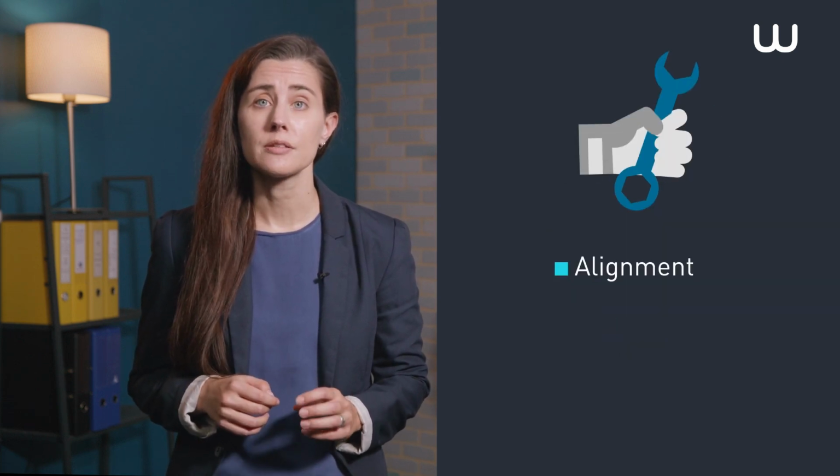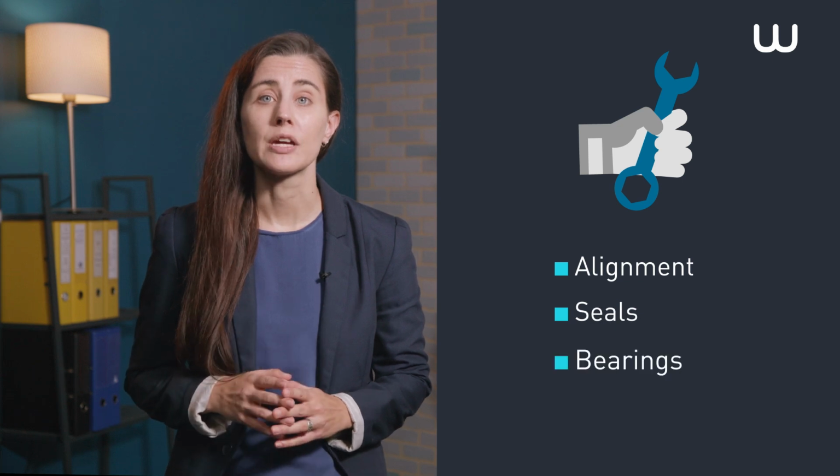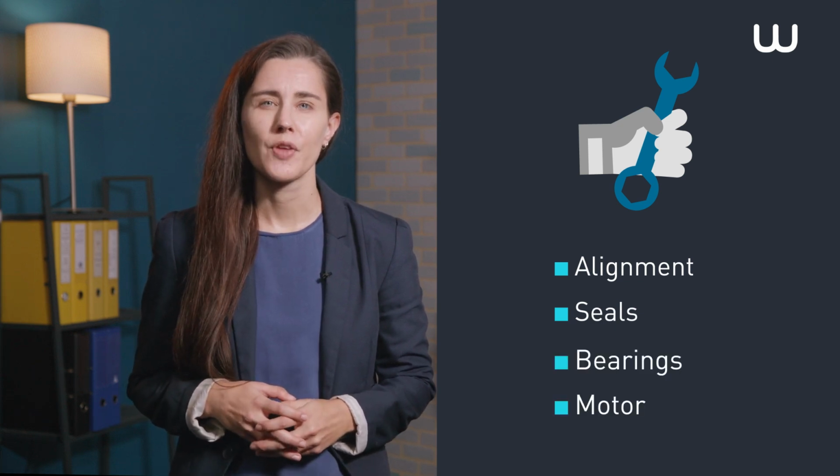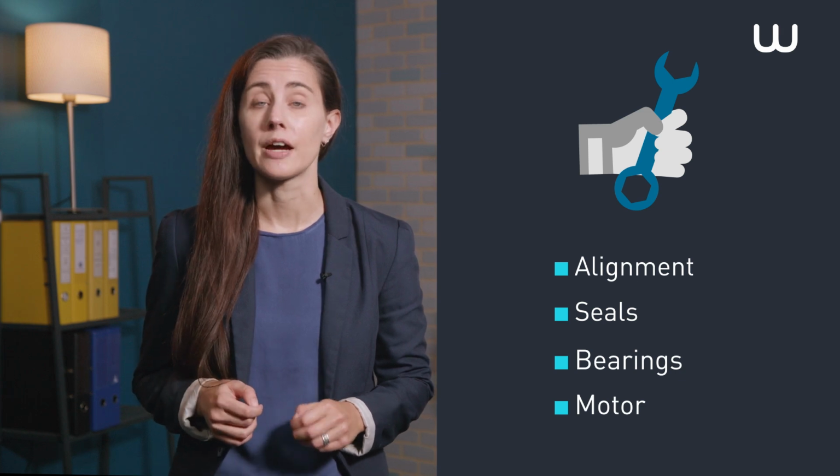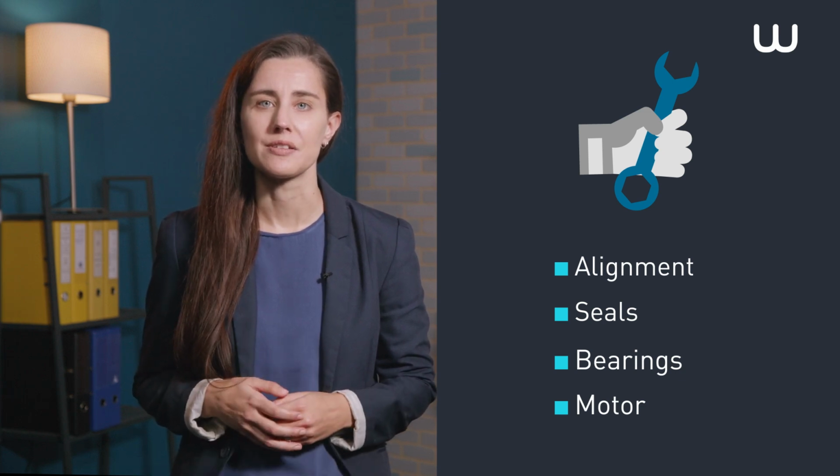Firstly, optimized, regular, and preventive pump maintenance is obligatory for all operators. This permits pumps to be maintained at maximum efficiency. In effect, in addition to specific energy monitoring, it is necessary to carry out checks and regular maintenance with respect to alignment, seals, bearings, and the motor. All of these actions permit the degradation of pump energy and hydraulic performances to be limited.